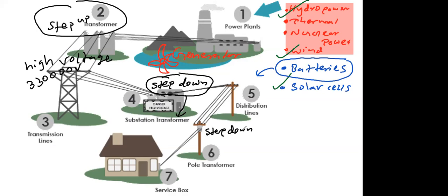Look at this, 1 2 3 4 5, the flow. Step down transformer. So there are 3 transformers used, right? Near the power station, 1 transformer, that is step up, and at the distribution subcenter step down, and near your house step down, because this very high voltage cannot suddenly be reduced to 230.